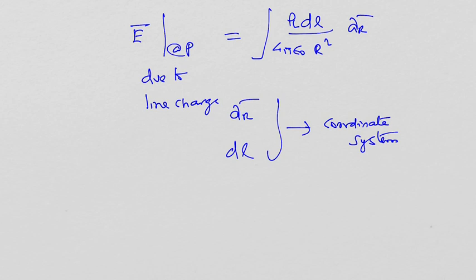E due to surface charge, for example. Or in the previous case, if you want me to explain with the help of a diagram, I am ready. See, I have a straight line or any other conductor over which charges are distributed uniformly with the charge density rho L. I take only a small portion, which is called dl. Now I take a point P, the point at which 1 coulomb charge is present or the electric field intensity is going to be observed.